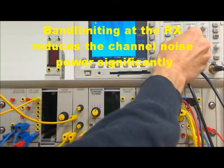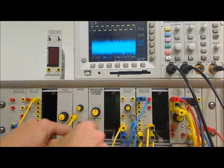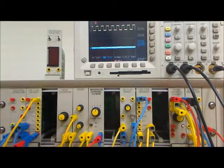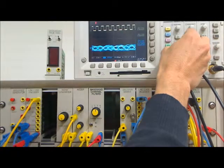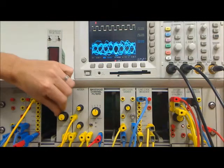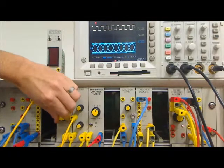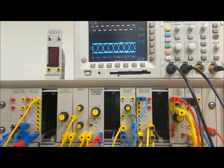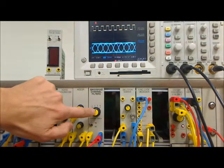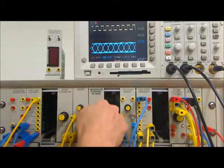If we put the noise back in, you can see that the signal in the channel is predominantly noise, but having a look at the output of the baseband channel filter, you can see that there's very little noise and it's predominantly signal with distortion and a little bit of noise. If I adjust the amount of noise by turning the noise generator to 0 dB, you can see that the signal is predominantly the signal passing through the channel and affected by the band limiting of the channel.